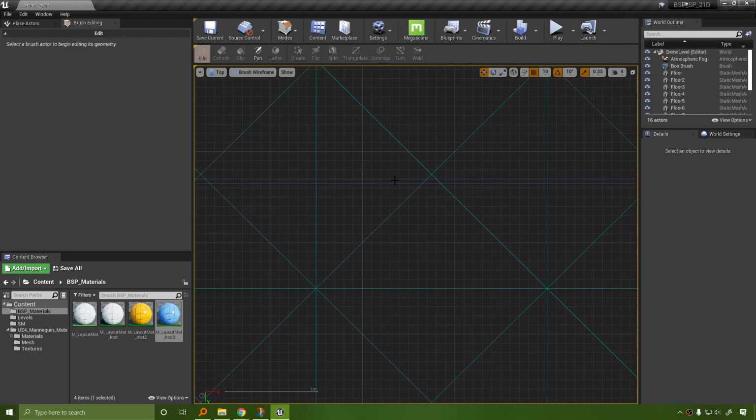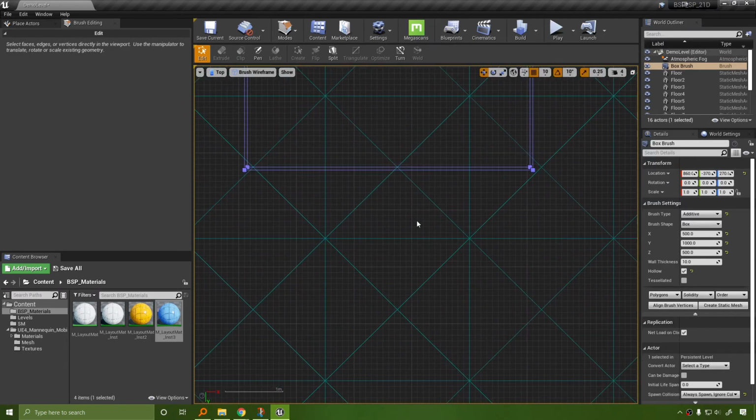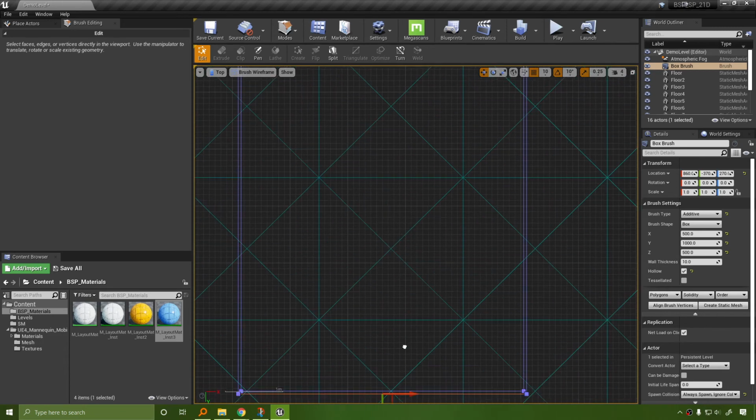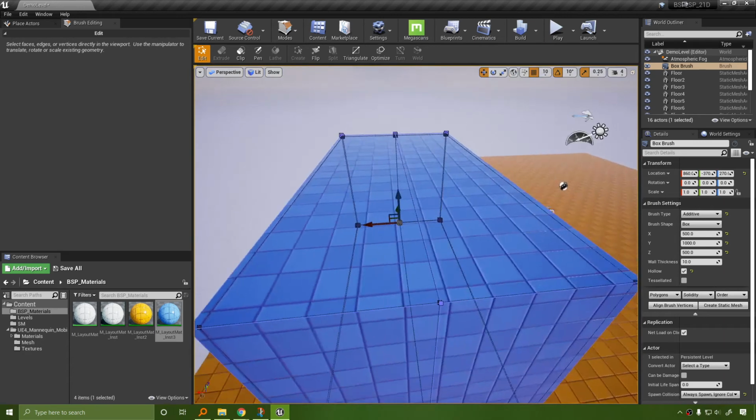Take a look. It looks like it's treating the outside wall. So I'm going to select this outside wall, and then I'm going to right-click and move down and select this outside wall just by control-clicking it. And then I'm going to split it. Cool. And then I'm going to go back to Alt-G to go back into perspective mode.